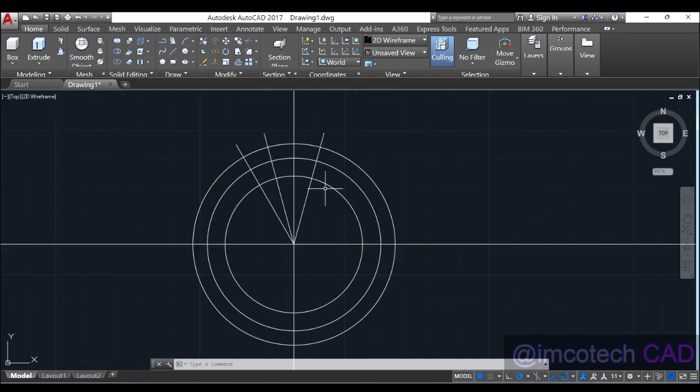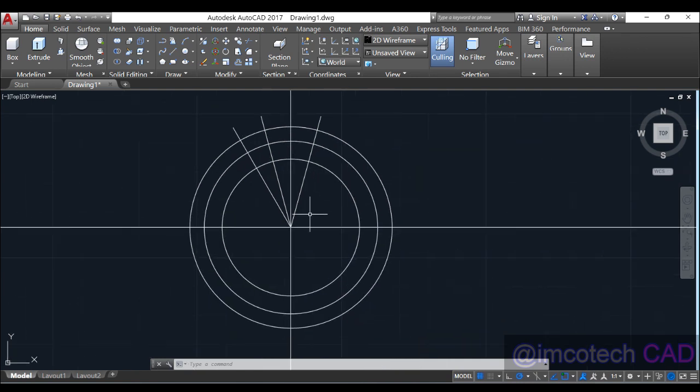Okay, how do we get the base circle? The base circle can be obtained by the intersection of the pressure angle lines, and the pressure angle is 20 degrees, right? So take a line, and draw the pressure angle from this place like this, because one tooth will be from this place to this place, right? So 20 degrees to this place will be 110 degrees.